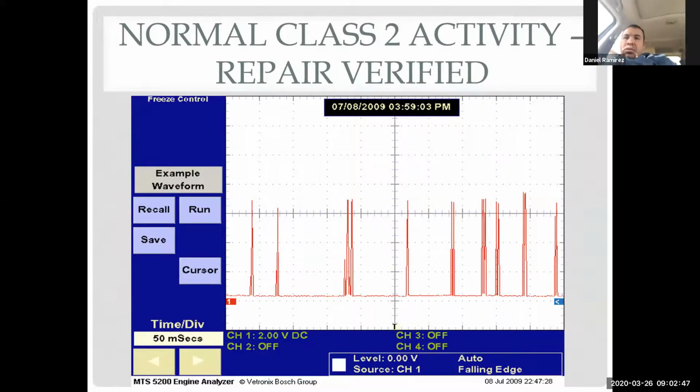But good questions. So does it make sense to you guys how I got here as far as the diagnosis, and how we could see that it's working, and how I traced down that 11 volts just by using the schematic and then figuring out the topography of the network and just isolating it and checking one thing at a time to find out where it is? Yeah, sure. That was a good case.